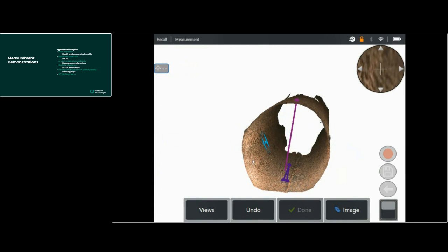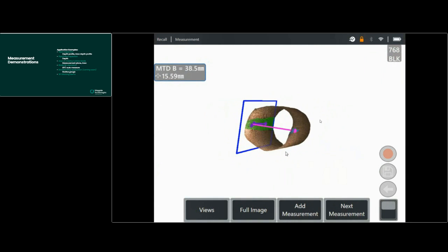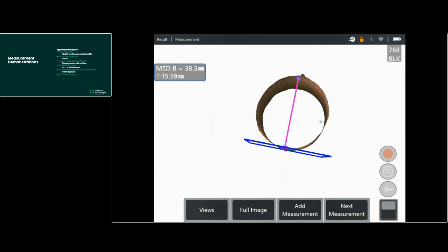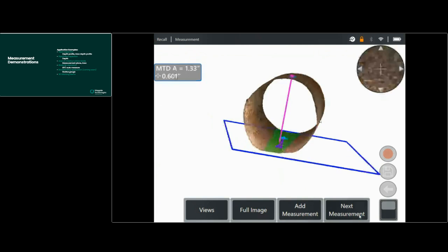the screen. So let's do that. Another reference plane and another diameter calculated. Pressing and holding the text box takes me back to Imperial. And yeah, 0.614 millimeters for one measurement, inches, 0.6 inches for the next. So this is almost 0.625, which it took me a while to realize, because I tend to work in metric, but that's almost 5/8 of an inch.